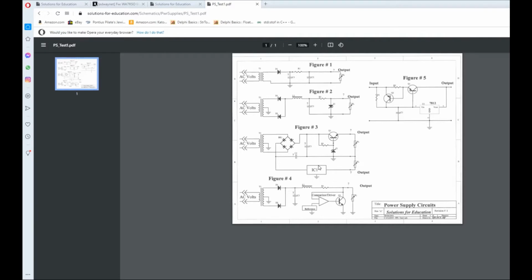And you do have to have a heat sink on this unless you're only drawing a little bit of current, this being the variable load. I'll show you later. This guy here, by the way, has about 23 transistors, diodes, and resistors in here. It's deceiving. It's a little TO-220 package, but it's got a lot of stuff in it that does very tight regulation. And you won't have any ripple coming off of this guy. It'll be very, very clean.